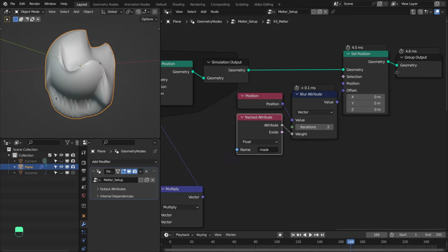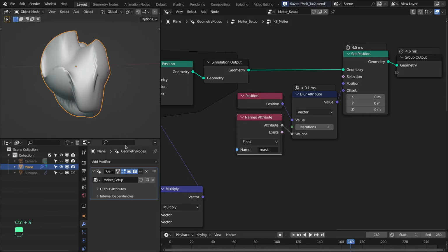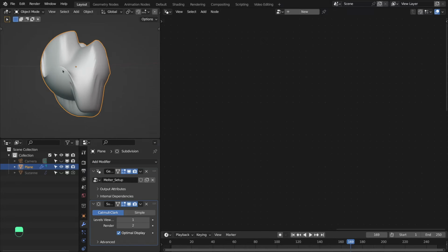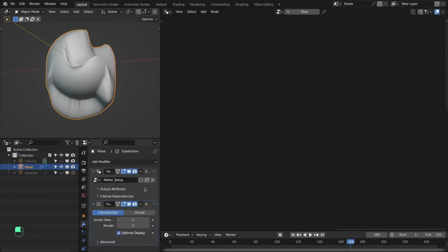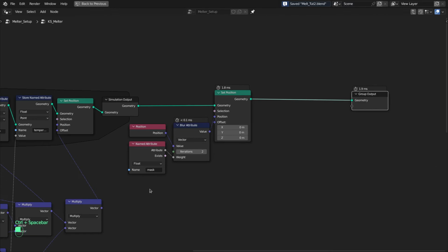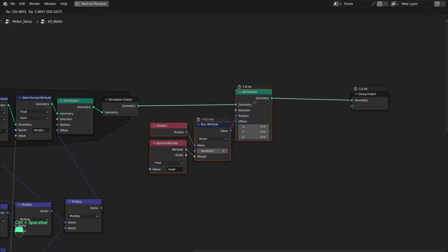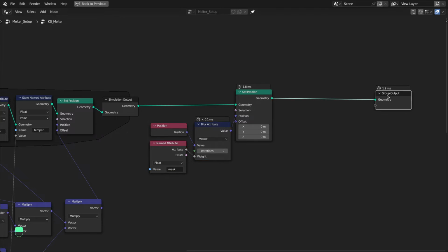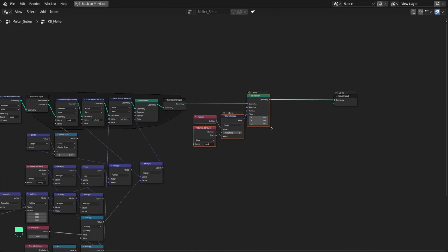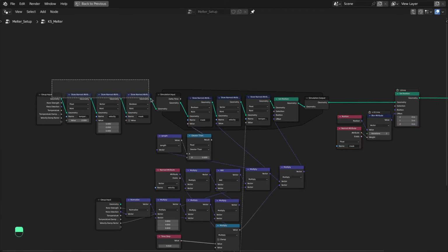So we have this smooth mesh, and on top of that we can add the subdivision modifier to further smooth the surface. See, okay. And next let's add the mask based on the velocity and temperature, which we will use in the material to add a different color to the melted and non-melted part of the mesh.